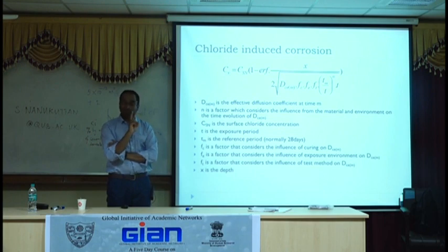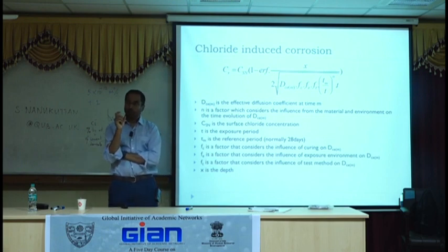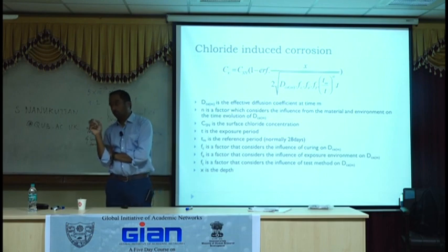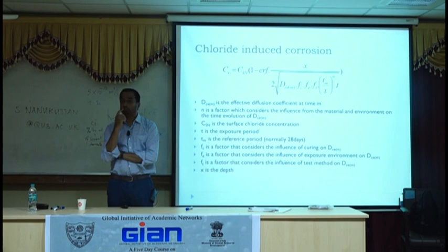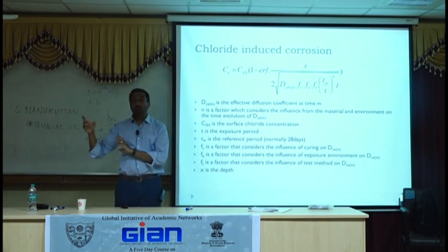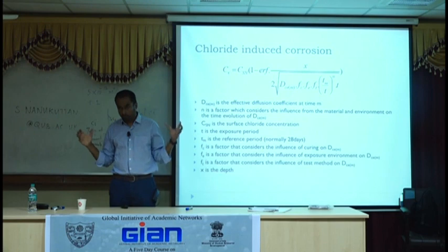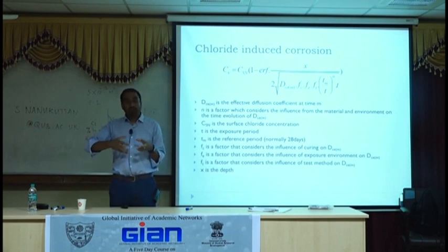Within 2 years, we've looked at different cement systems. One was a normal Portland cement, and one was a heavily blended cement with something like 79% replacement. Normally, the 79% replacement will give you low diffusivity much earlier on because of all the reactions happening, and the microstructure will refine further and further, which is great.